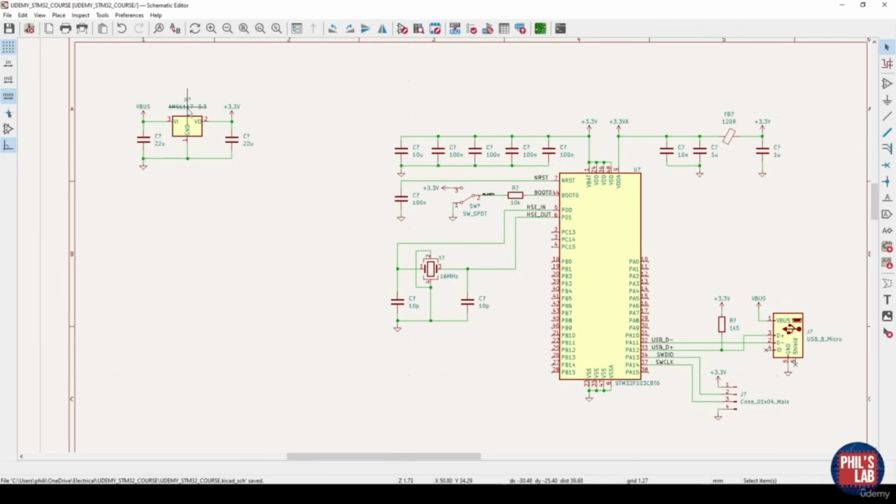The regulator itself will have some sort of noise suppression, so this will do for this circuitry, but it's always advised when you're using USB, at least to power your device, to perform some additional filtering. For the sake of time, and because this simply just worked, we'll stick with this.